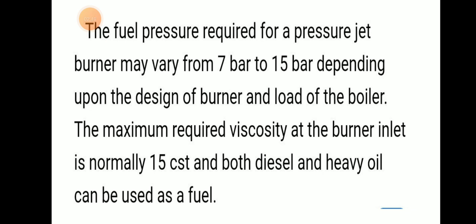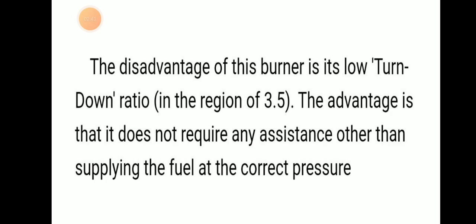The disadvantage of this burner is the low turn down ratio, that means in the region of 3.5 and down. The advantage is that it does not require any assistance other than supplying fuel at the correct pressure.